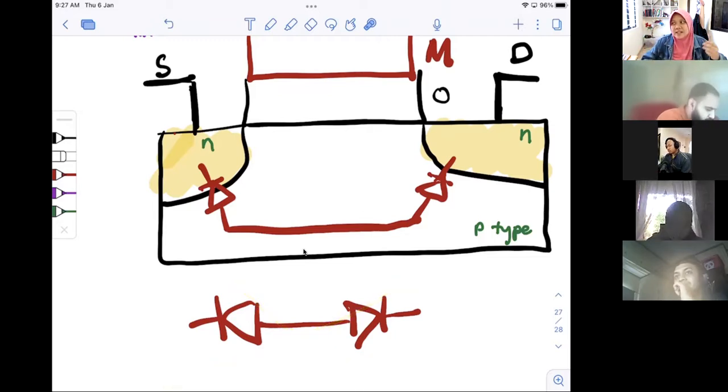That's another good thing about a MOSFET: the leakage current will be very small, because when it's off, the structure is naturally a back-to-back diode. Let's say you have a handphone, right? When you turn off your handphone, do you want it to use the charge or the battery? No, right? You want to save it. The battery will last forever if you turn it off.